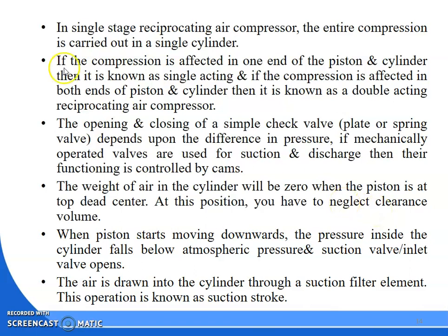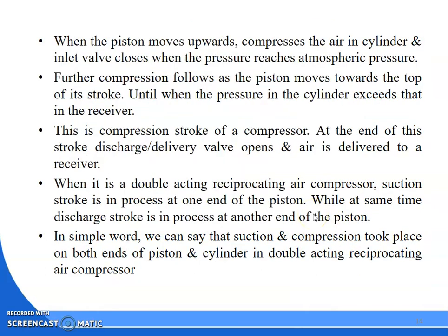So when the piston starts moving downward, downward means from TDC to BDC, the pressure inside the cylinder will fall below the atmosphere, and the suction valve, the inlet valve, will be open. How? Because of the pressure difference, and air will be drawn into the cylinder through the filter, and that stroke is known as the suction stroke.